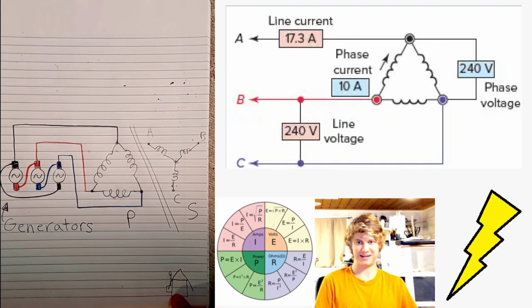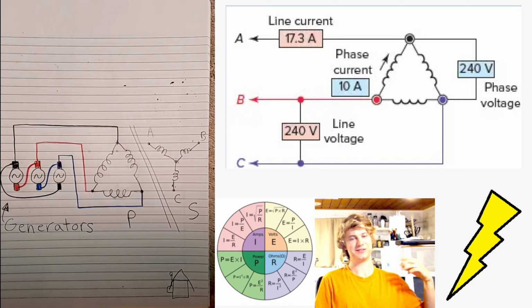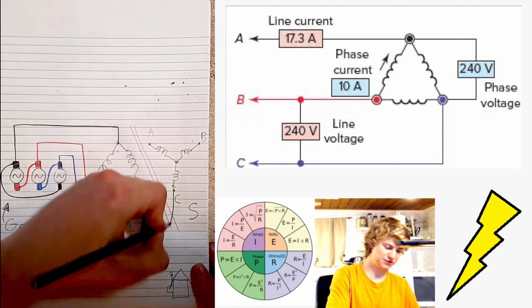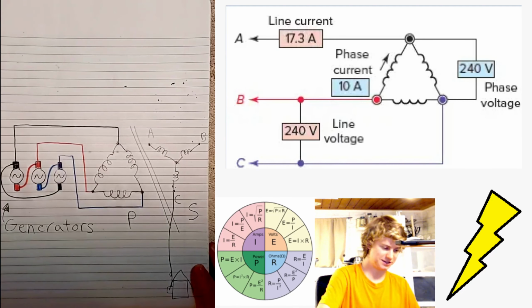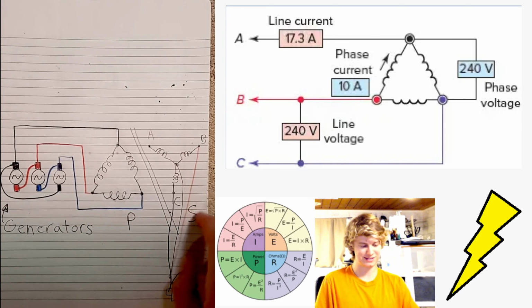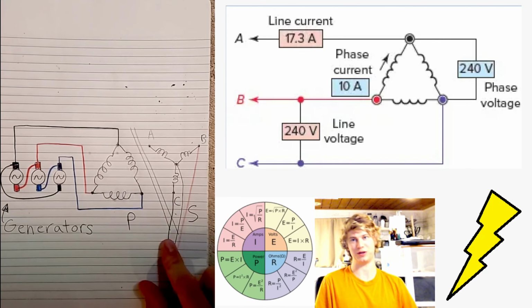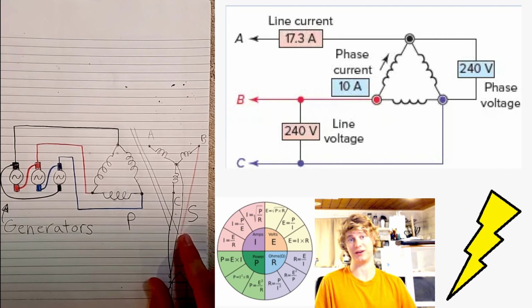Okay, so in the circumstance of a house, you have the outside service with a weatherhead, so overhead service connection. You can take any two of these three phases. Here we're just going to take B and we're going to take C, and of course you need that neutral. I'll just do pencil color, and you see where the neutral's coming from is the center of this. So again, we don't have a two-phase system, we have a single-phase system capable of doing 120 or 240 volts depending on how we wire it.